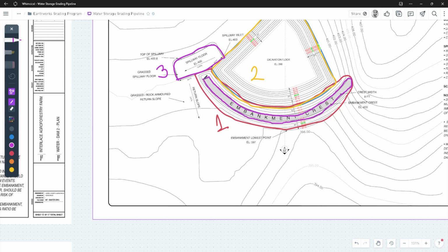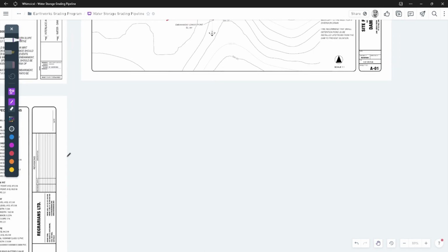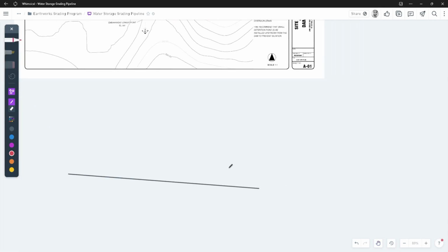And if we look at it from the side, if we have the existing ground right here, the crest at that point is going to sit above the surface. So we're going to embed that with elevations. Let's say this is at elevation 100, and down here we have elevation 95. So our crest will be 5 meters above the existing ground if measured from this point.